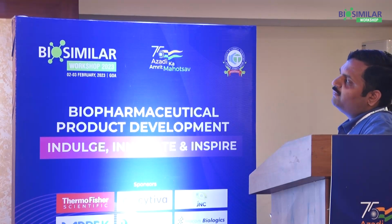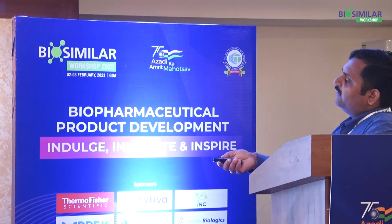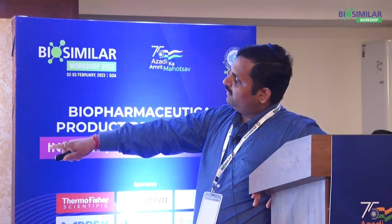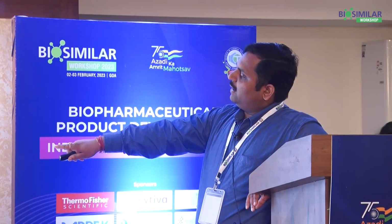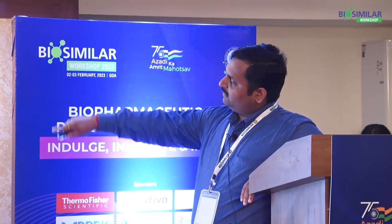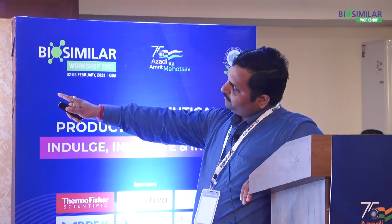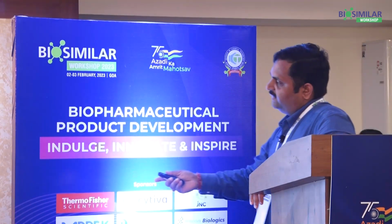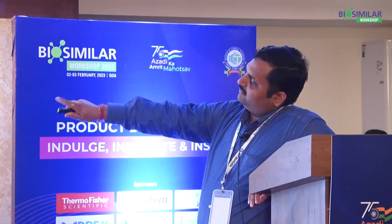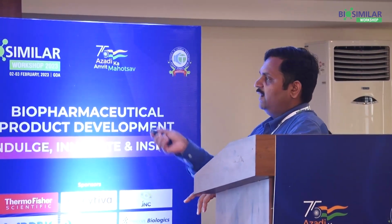Now for the model framework for the continuous process, we have to understand this graph. As you can see, the line going up is a breakthrough curve, and the point where it starts is the 1% of the breakthrough. In a continuous process, anything coming through in the breakthrough needs to be captured on the second column. So the area under the curve is the area captured on the second column, and the area above the curve, which we are targeting and denoted as S, is the amount of product which will be on the first column. So this is very important.